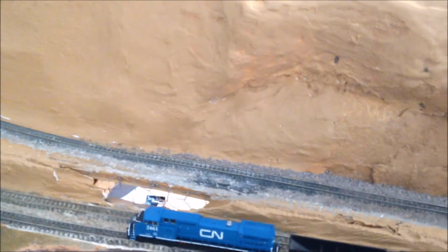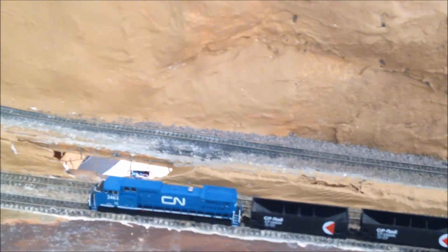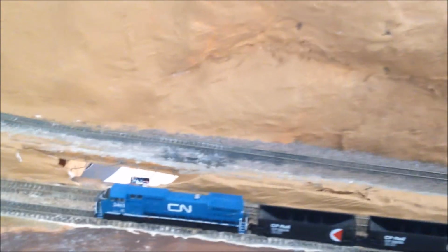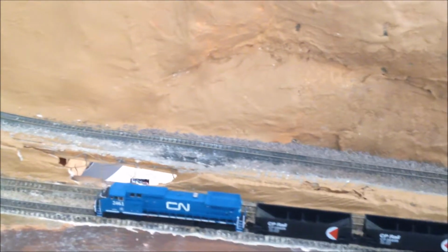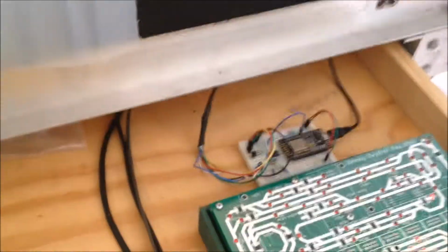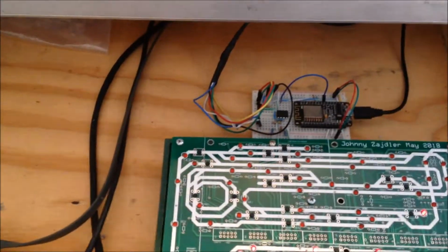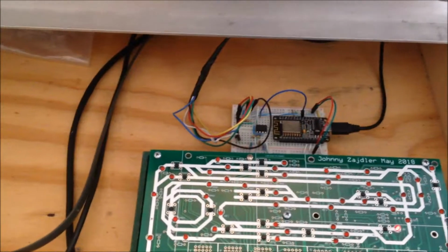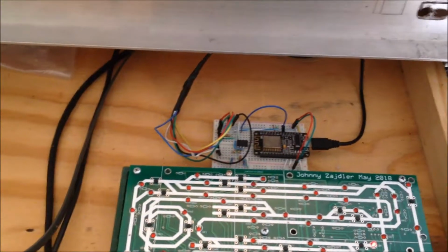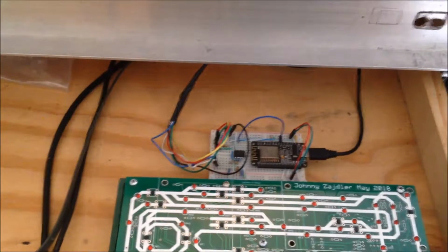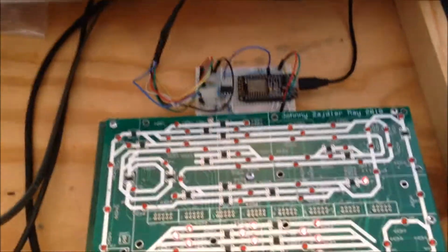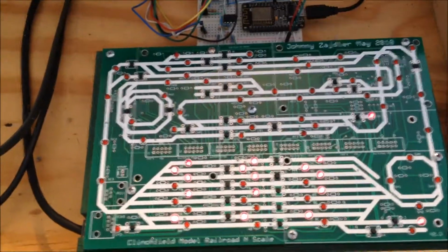The next step would be Digitrax. They use their LocoNet, and LocoNet is a separate bus using a telephone-type jack. Now you have devices that are bi-directional, so they send information back and forth across the bus. Just like DCC sends on its bus, the LocoNet bus sends its information on the LocoNet bus. Everybody listens, but everybody can also give feedback about their position or what's going on. So in the case of my panels here, you see I had built this one.